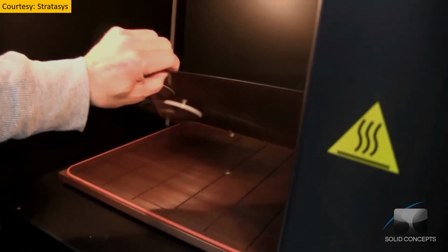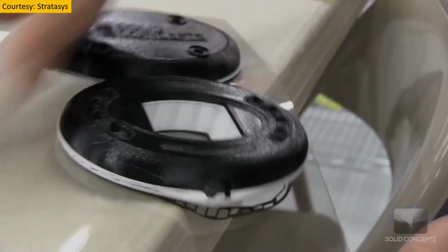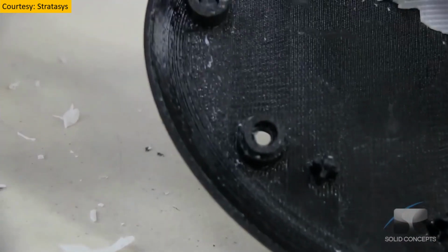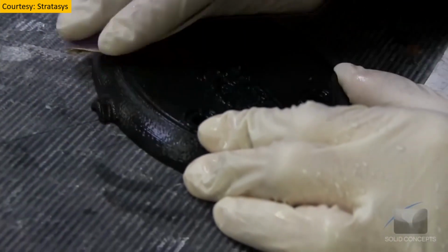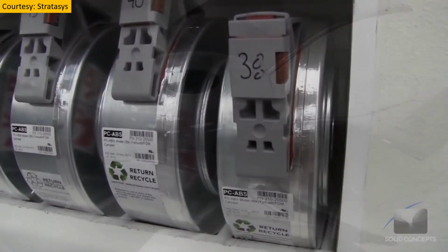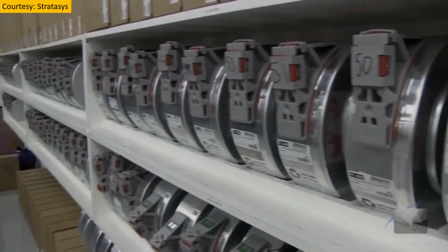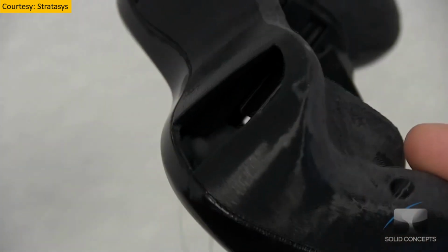The process repeats itself and builds the entire part, and then we take the substrate out and remove the part from the substrate easily. As much as possible, we remove the support by using mechanical tools, and later on we put the component into the waterworks where the support material is eaten away, and after that we give a finishing touch to the final parts, such as grinding and some chemical processes, and create the final finished part.